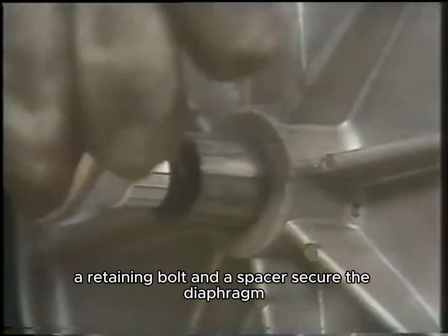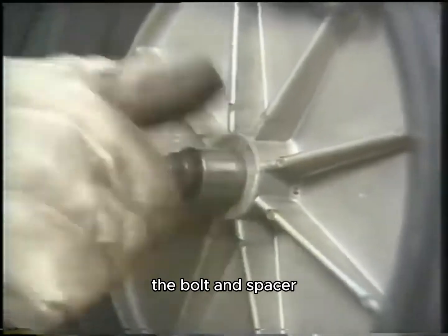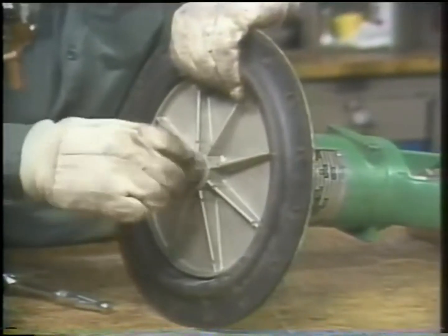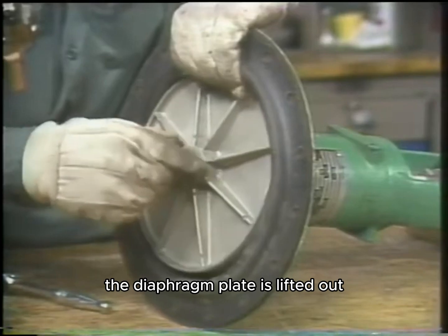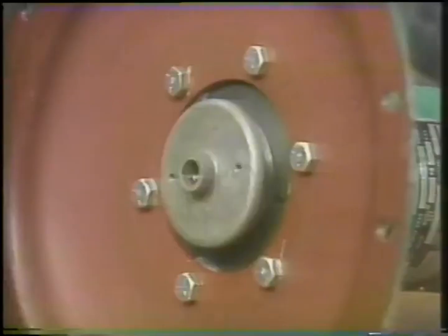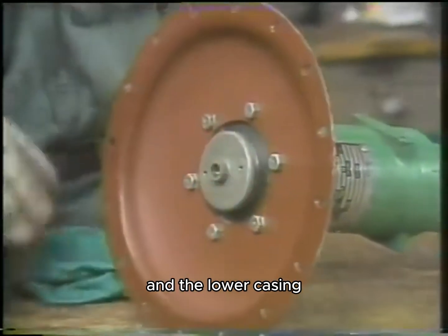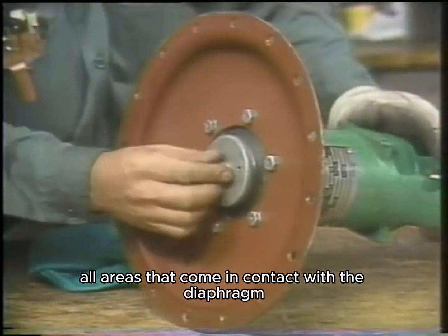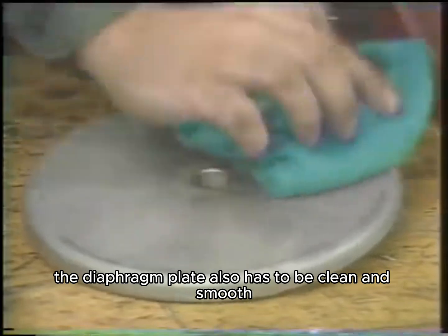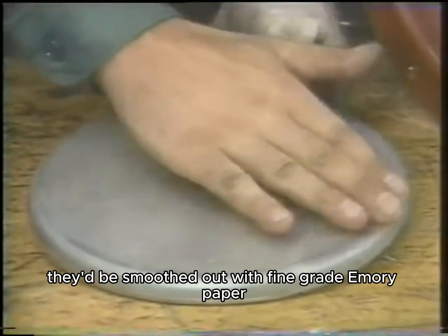On this actuator, a retaining bolt and a spacer secure the diaphragm and its plate to the actuator stem. The bolt and spacer must both be removed to free the diaphragm for removal. Once they're out of the way, the diaphragm plate is lifted out, and the diaphragm is pulled from the casing. Before a new diaphragm is installed, it's a good idea to wipe off the top of the stem and the lower casing. All areas that come in contact with the diaphragm should be inspected for any rough areas that could damage the diaphragm. The diaphragm plate also has to be clean and smooth. If any rough edges were apparent, they'd be smoothed out with fine-grade emery paper.